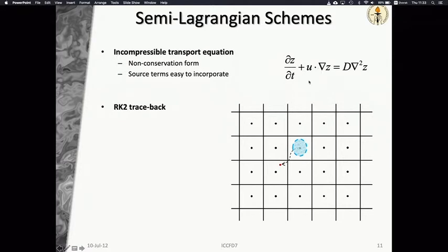You're not guaranteed that u is the same at all grid nodes. So this u can be 2 meters per second. This u would be 1 meter per second, but in the opposite direction. So if you recreate your grid after moving all the grid points, what happens to the grid? You have to interpolate the data. Yeah, that's exactly the concept.